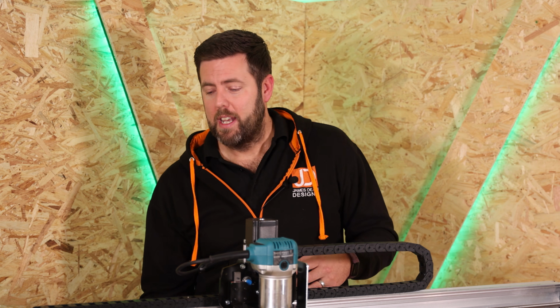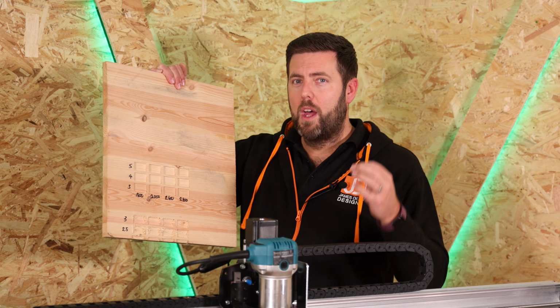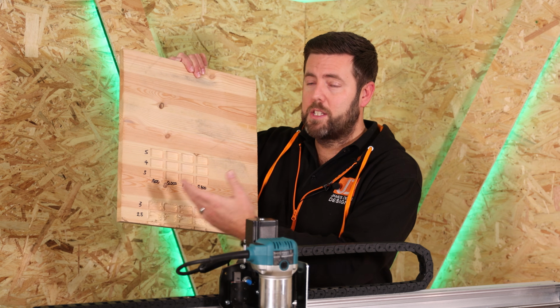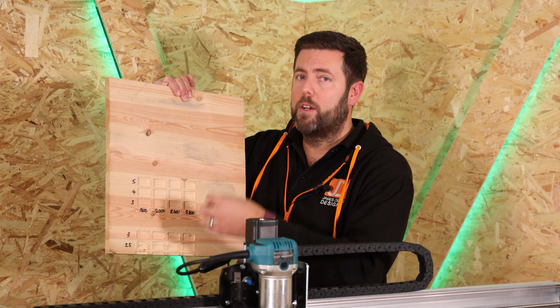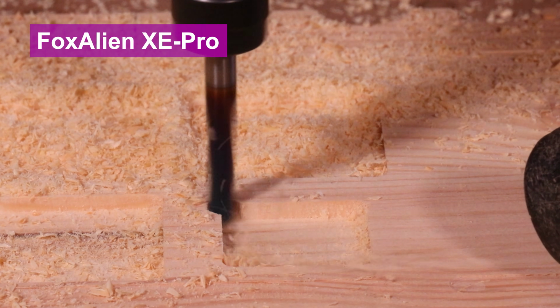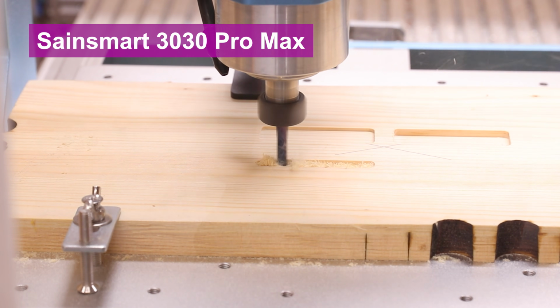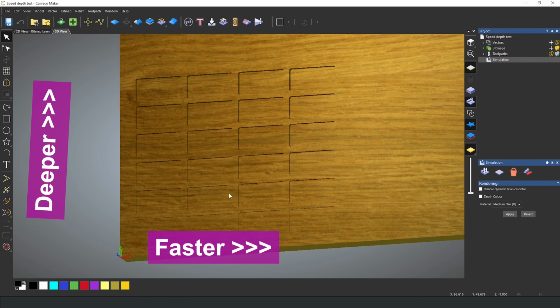And this is how I basically dial my settings in for the machine, not necessarily the bit that I am using. Now, when you come to do tests, I do something like this. You don't see it much in the CNC world, but you see it all the time in the laser community. They call it a power scale grid. And it's ultimately about just doing the same test over and over again, but either increasing the speed or increasing the depth. Obviously, you start very conservative and start to build your way up. Now, when you're doing one of these tests, it is really easy. Just do multiple squares in your software, and as I say, either increase the settings one by one and just run them through step by step.